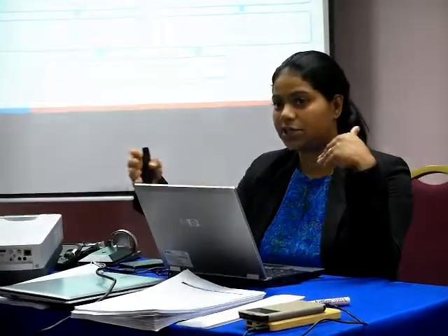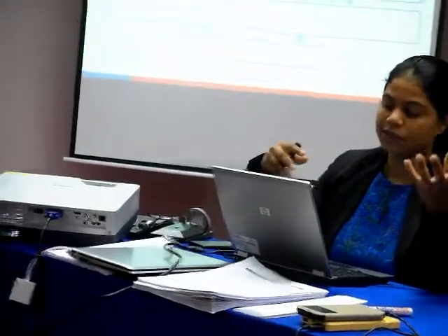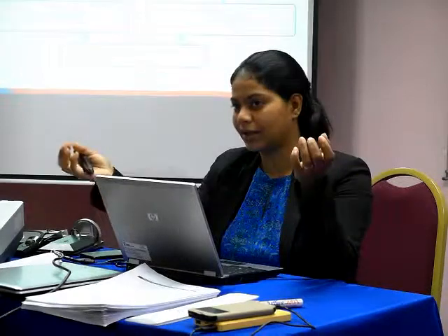And like I mentioned just now, we capture the UV, measure some leakage current, and then we are going to correlate this charge with the leakage current, and finally perform electrical tests and also mechanical tests. Mechanical test, we want to see the strength of the cap and pin type of insulator, and electrical test to see how much it can still withstand after going through all this accelerated aging. And finally, with all these results, we will be able to predict what is the remaining life of the cap and pin insulator.